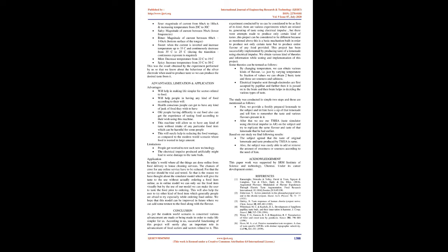Salty: magnitude of current around 50 µA, at lower frequencies. Bitter: magnitude of current between 60 µA and 140 µA, on the bottom surface of the tongue. Sweet: when the current is inverted and temperature is increased up to 35 °C and continuously decreased from 35 °C to 25 °C. During the transition, continuous exposure is required.